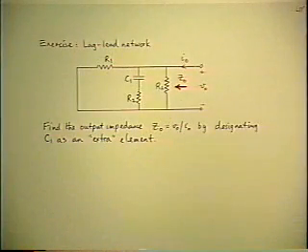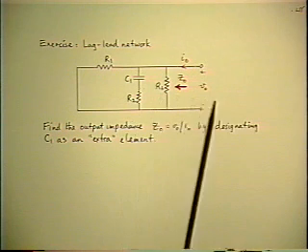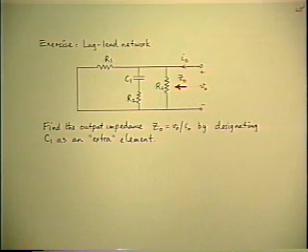Here's an example for you to work on, the same network, but calculate the output impedance. Using the extra element theorem to throw away the capacitor and then put it back using the theorem correction factor. Output impedance is also a self-impedance. So you can use the same shortcut.